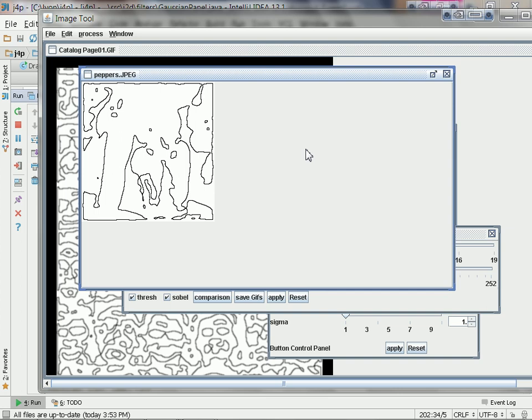Now, what you have here is a set of pixels in X and Y. Some pixels are on, and some pixels are off. But none of them represent a vector. None of them will tell you, go to this location and fire your laser. And so what you want to do in a case like that is have a series of line segments that are created from the edge detected image, and those line segments ideally would be connected. Connected line segments would enable the laser, when it's on, to continuously draw.